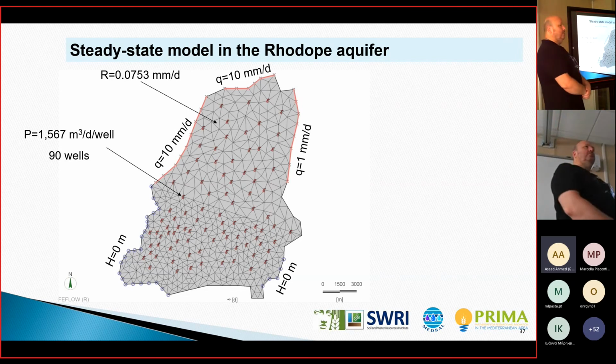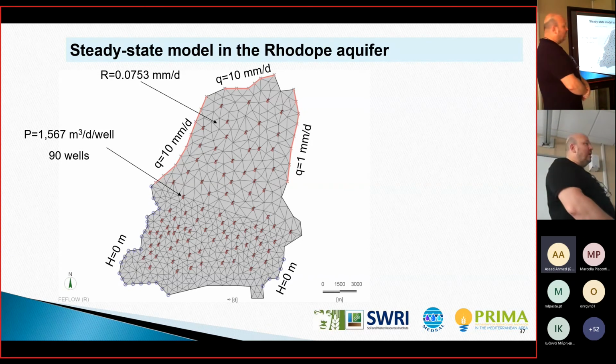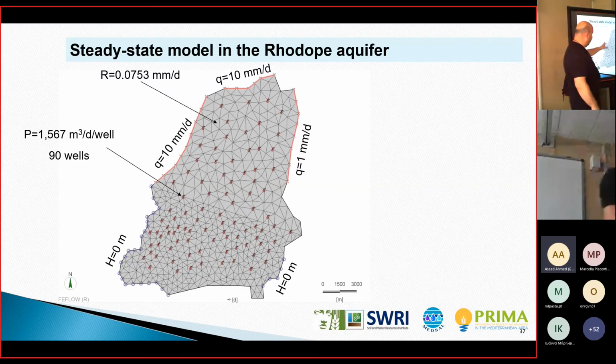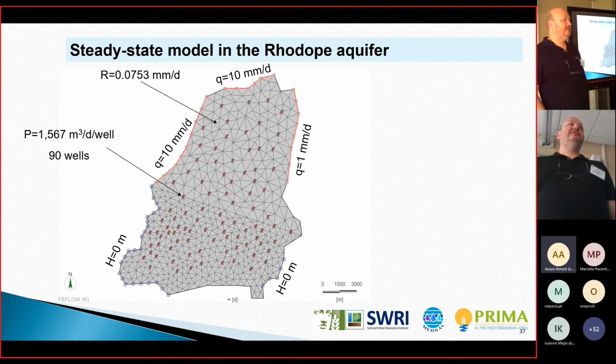You can also do it in another way if you know the geological formations that we showed before. And if you are experienced to translate these numbers, you can convert this to the boundary condition, or you can combine these two methods. Or this could be your initial estimation, and using the model calibration, you can find the final values of these inflow rates. Is this okay?